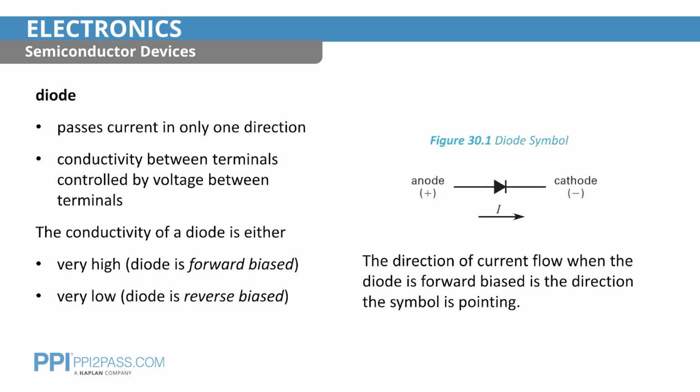Also, on the exam, or in general, you're going to experience voltage drop across diodes. Most of the time, the problem will tell you what the voltage of the diode is. If it does not say anything at all, for the FE exam, you're going to assume 0.6 volts. I know in a lot of colleges they teach 0.6, some colleges teach 0.7, but the NCEES prefers using 0.6 if they don't state it in the problem.